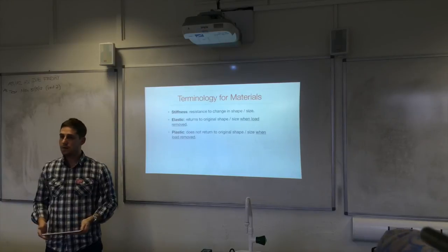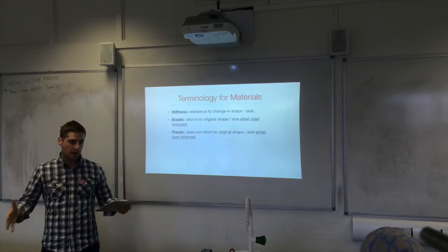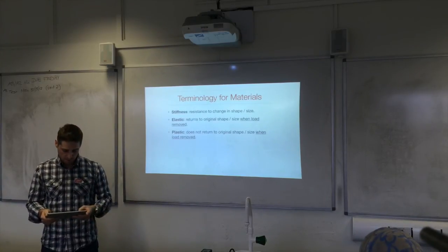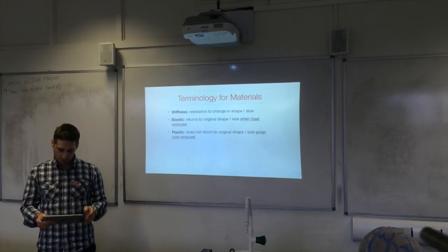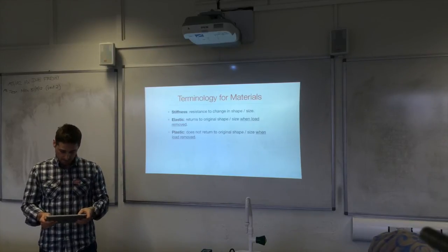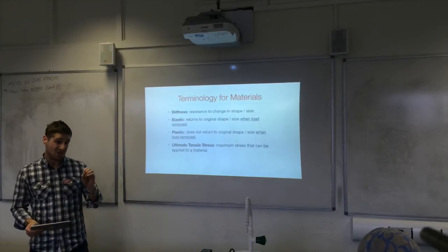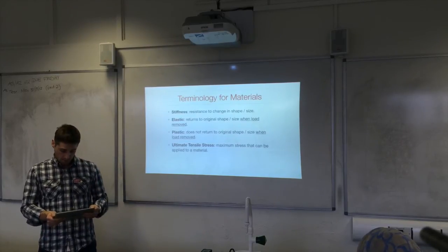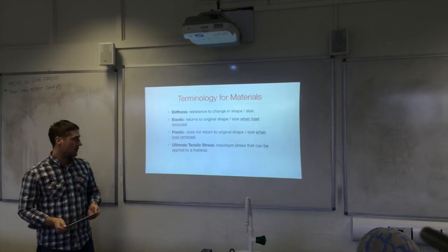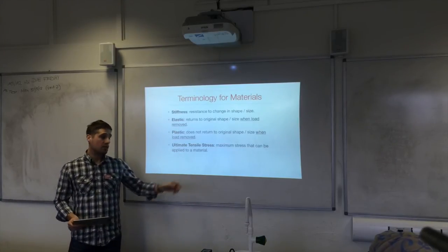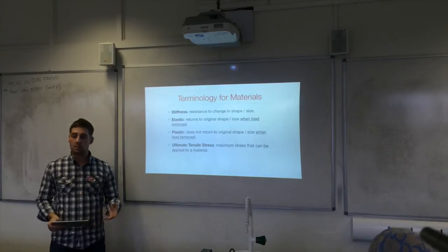That's the key thing. You have to remove the load, and then it will have the opportunity to return back to its original length. Materials that deform elastically usually have a straight line in the stress-strain curve. The ultimate tensile stress is the maximum stress that a material can take.